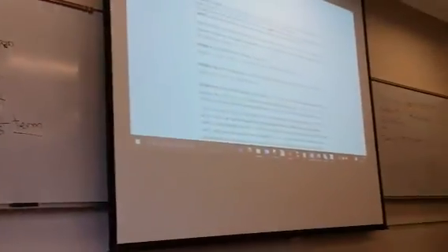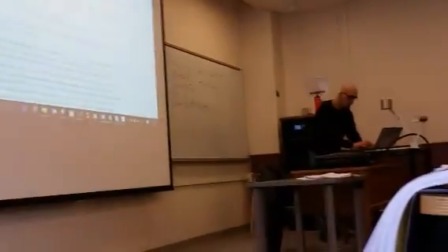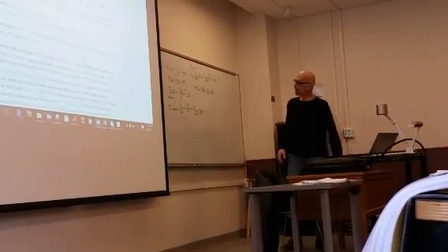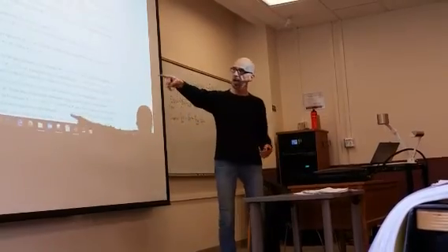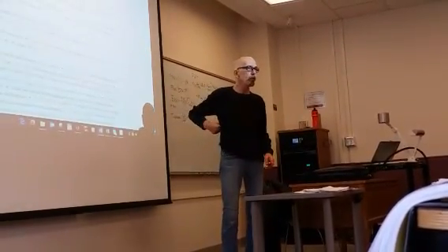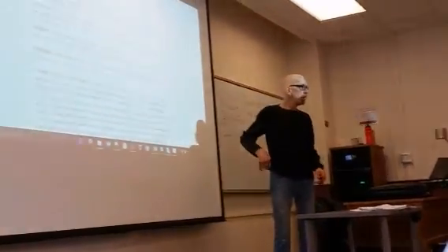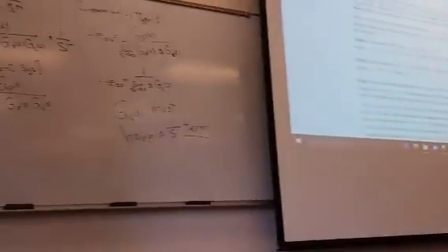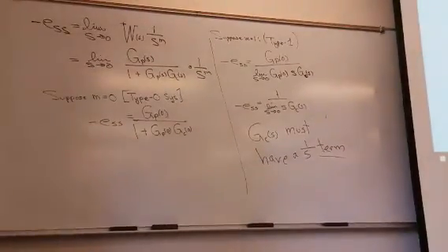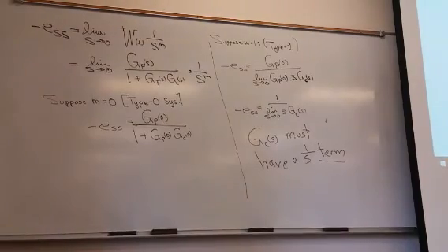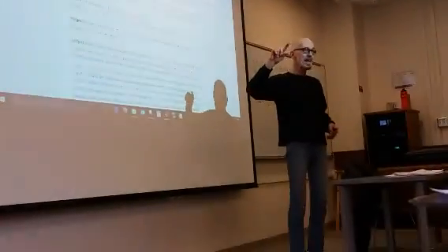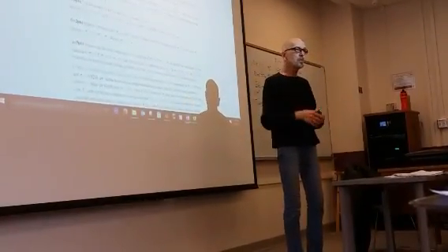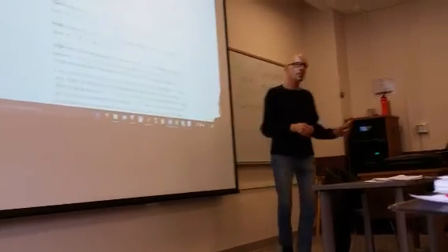Let's take the simplest controller right now. What's the simplest controller that'll satisfy that steady state error spec? It's integral control, isn't it? Just K over s. That'll satisfy the steady state error spec, right? And we can choose the K as big as we want so that 1 over K makes a small steady state error and everybody's happy. Except we don't have time.